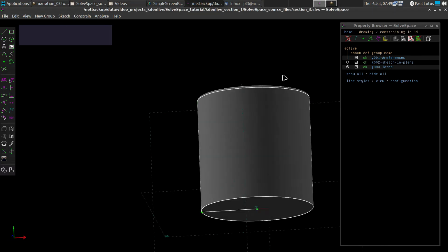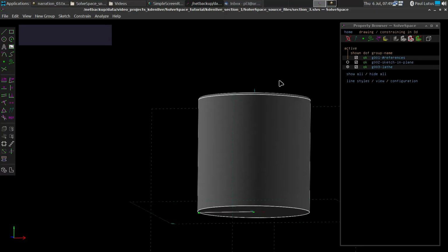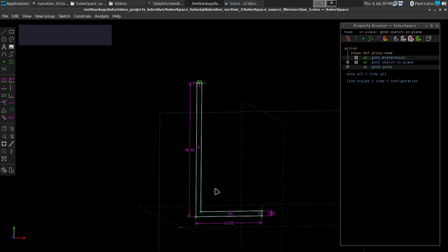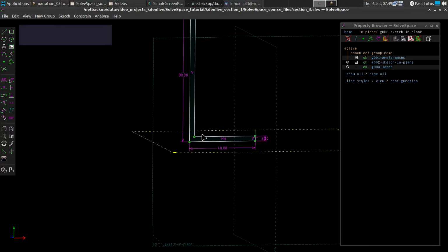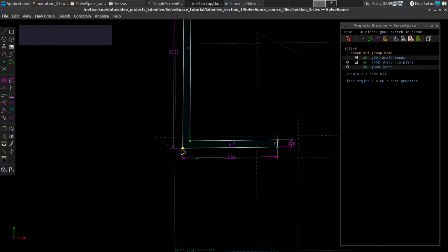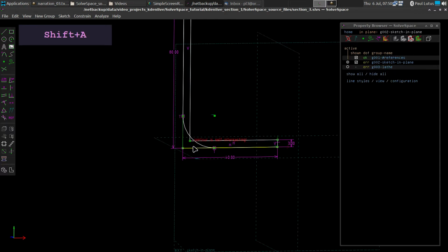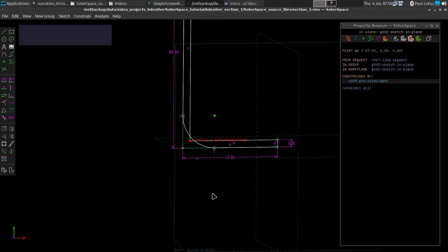The top of the cup looks better, but the bottom is still a straight line. So let's play with that a little bit. So let's go down here. And I would like this to be a curve. And so I just selected a point. And this one here, which is called tangent arc, Shift+A, does this. It creates a tangent arc. It creates two new points and draws an arc between them. I'm going to do the same thing here.